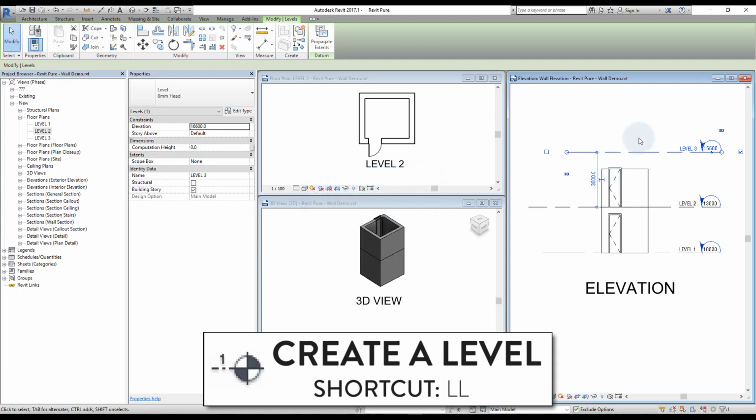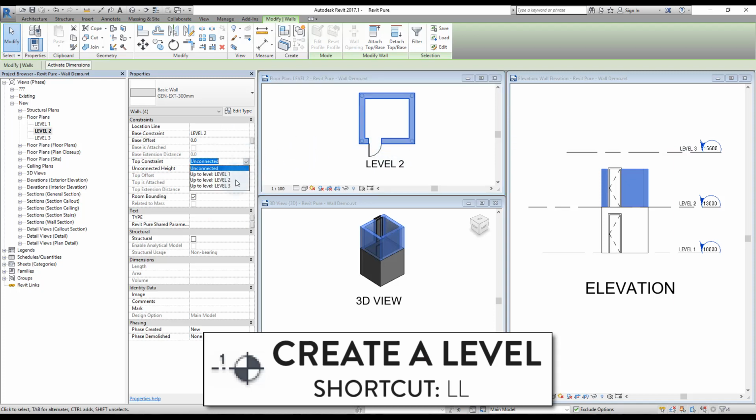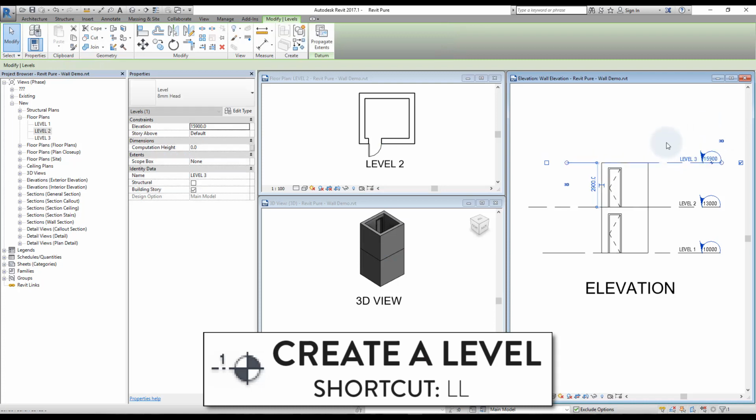In Revit, elements are constrained to levels. For example, we can constrain the top of these walls to our new level. When we change the height of a level, the walls follow. You can type in a value to change the level elevation for more precision.